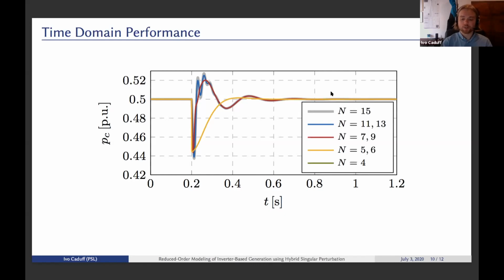Suddenly a large error is introduced, indicating that the last state reduced, going from order 7 to 6, contained valuable dynamic information. This state, theta S, again the PLL state, was previously declared as fast and not very fast, and therefore should be reduced using first order singular perturbation.